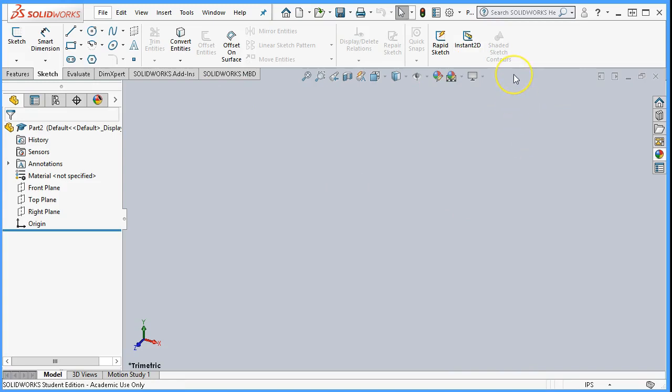When we actually get into a sketch and go to create something, you'll find out your preference on the shaded sketch contours to go with. So opening up a sketch, do be careful with, and we'll get it to expand out here, the 3D sketch. We're not ready for 3D sketches. 3D sketches operate in, well, all three planes. They are a very powerful tool, but we want to stay in the sketch. So you don't really need to even expand out the arrow on this one. Just clicking on the sketch will take you into the command. So we'll get that in a second.